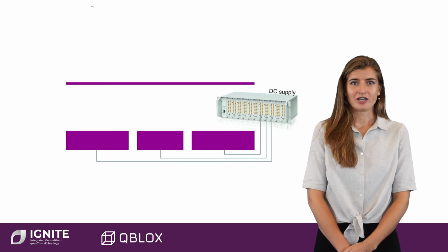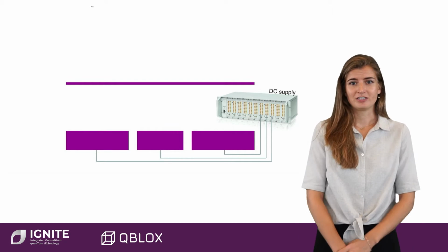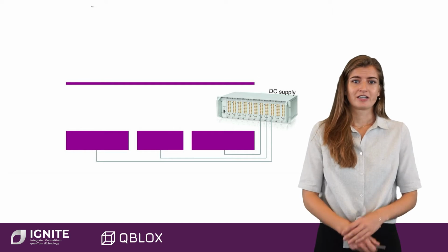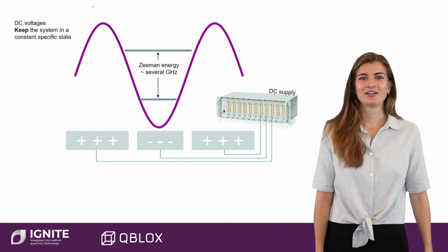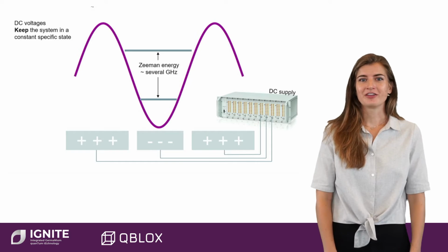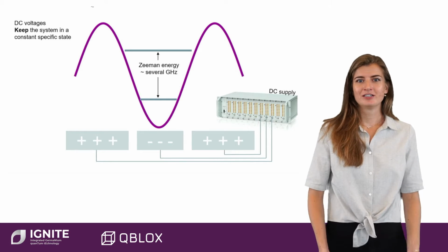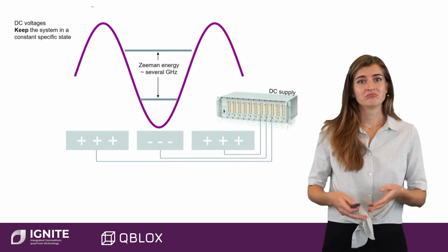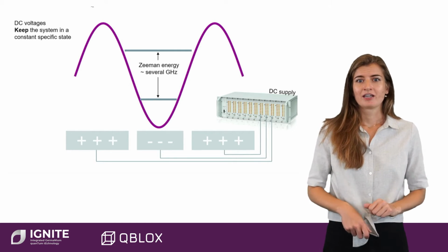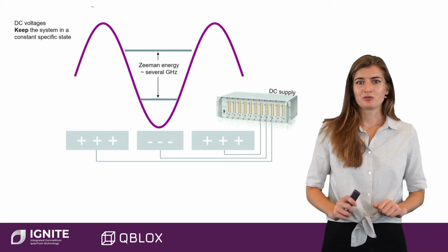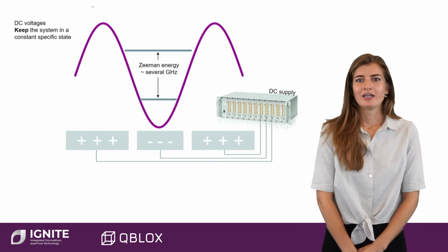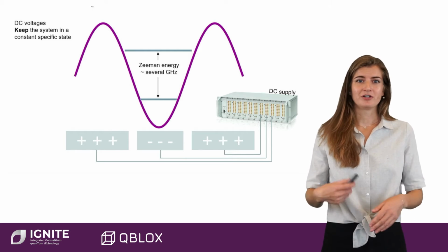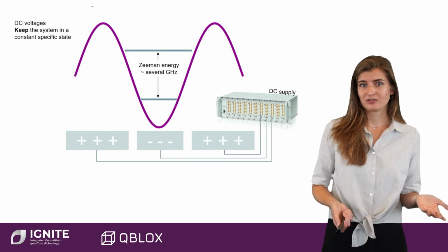These sources are designed to provide an ultra-stable voltage and current output and are used to set certain conditions that are kept constant during the experiment. For spin qubits in germanium, we can think of the voltage barriers that are applied to deplete certain regions from charge carriers. In this way, a quantum well, or quantum dot so to say, can be engineered to capture single spin-full charged particles. In this case, the voltage barriers are tuned to capture holes. Changing the polarization would allow for the manipulation of electrons.